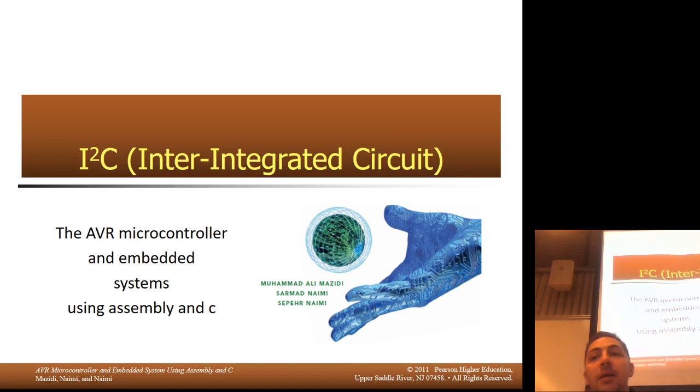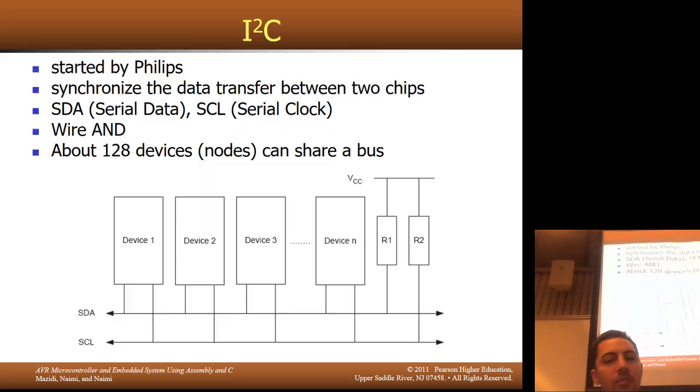Okay, last chapter, and this is what we need to finish off the last lab, integrated circuit bus. We've talked about three main methods of communication in the third part of the course: UART, SPI, and now we're going to talk about I2C, or integrated circuit bus. And high level, this is all you need. You need a bunch of devices and two wires. The only external components you need are some pull-up resistors.